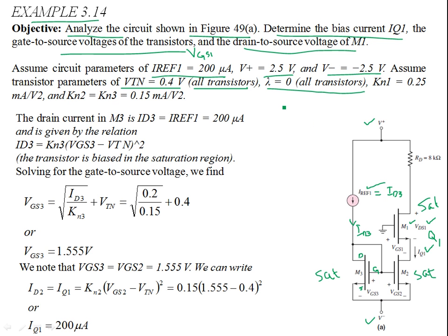That means we are considering the ideal IV characteristics. So you can write this as ideal MOSFET devices, ideal MOS devices. These are not the actual devices, but the ideal MOSFET devices, so you don't have any forward resistance. In the saturation region, ID is independent of VDS. So it's an ideal device, with VDS on one axis and ID on the other.